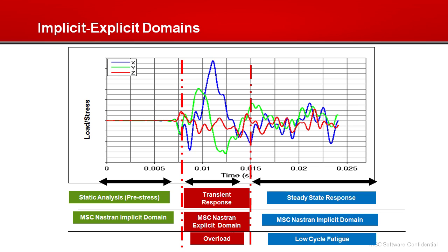This is a very important chart since it will demonstrate the steps we need to take to do a full run fan blade out to rotor dynamics simulation. There are basically three stages. The first stage, which is here, is a pre-stress analysis of the running fan blades.